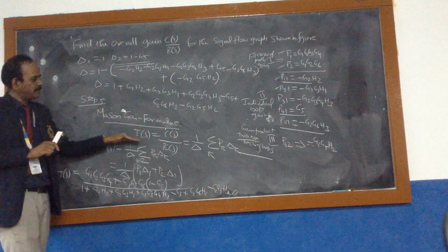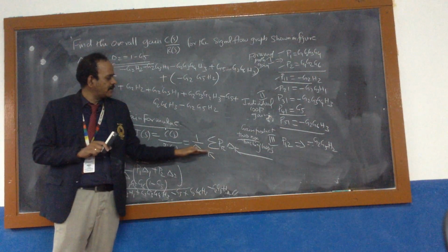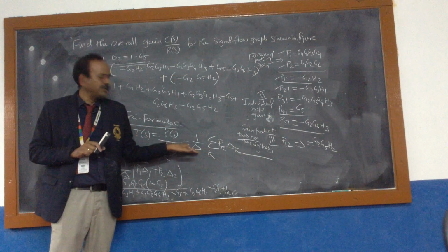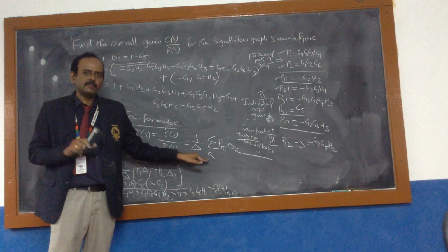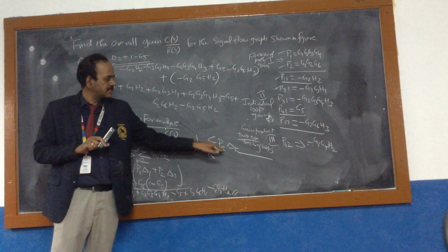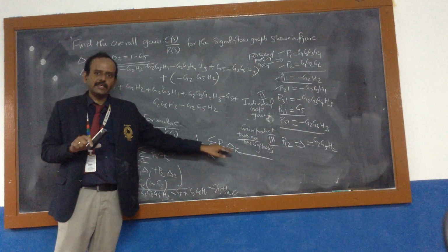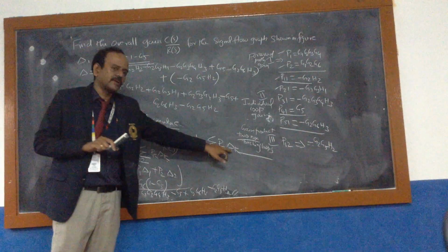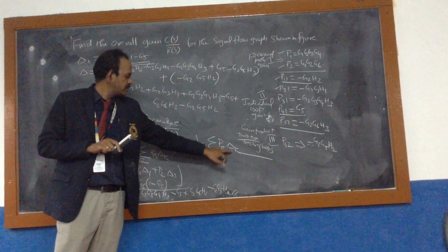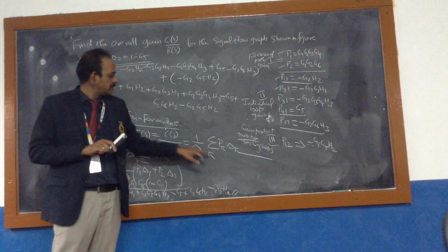Okay. So the final formula, keep in mind whenever they ask you for 2 marks also, we have to write the corresponding values. What is the del formula? What is the k? Okay, k is the number of forward paths, and what is the del k? Del k represents the 1 minus of the part of the graph which does not touch the kth forward path. Like that we have to write. Okay, then we have to write the formula fully.